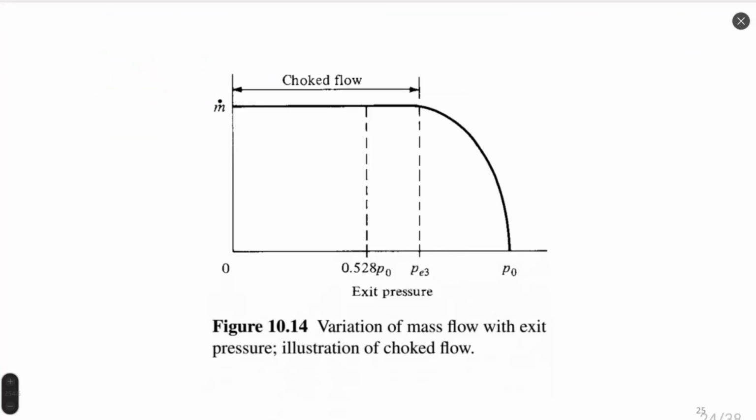You can see on this figure right here, representing to us in coordinates of pressure difference or pressure gradient and mass flow rate. For all pressure gradients which would be significant enough to accelerate to Mach 1 in the throat, so all cases starting from this point and until the end, this blue line will be having Mach 1 in the throat.